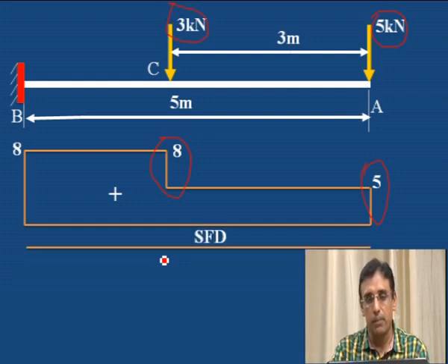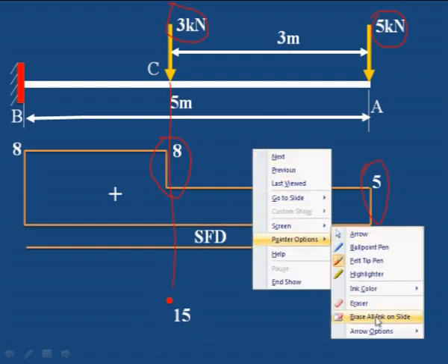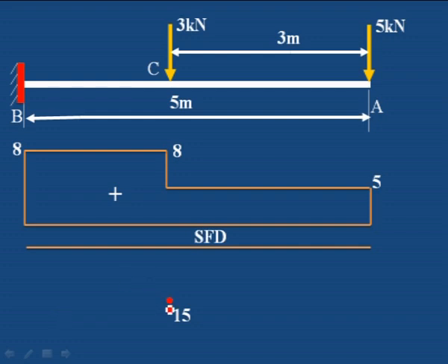Next, bending moment diagram. For drawing a bending moment diagram, first draw the horizontal line, because it is a negative moment, top line, horizontal line. Then we have to mark the points. Here it is 0, this point is 0, and exactly below this point we have to take 15, whatever calculated value, 15 kilonewton meter. Then 31 kilonewton meter is the fixed end value. Mark the points 31 kilonewton meter, 15 kilonewton meter, and 0 point.